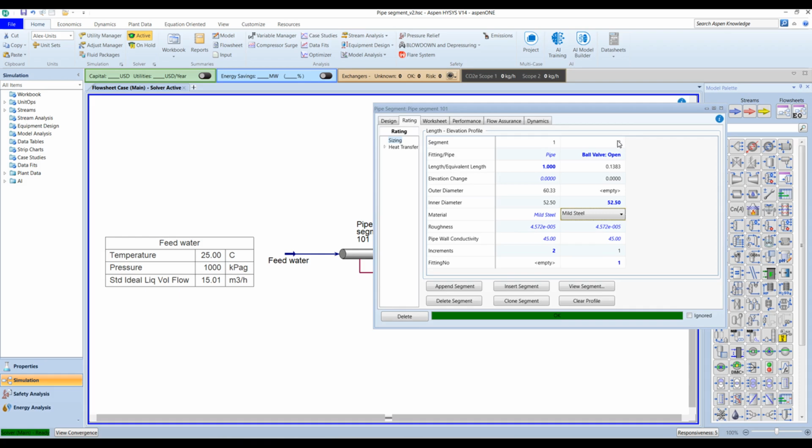And at the end of the ball valve, we want to have that 174 meter pipe run. And to do that, you don't have to do anything fancy here. You just come here, you clone this one, because this is just a pipe, right? This is a 1 meter pipe, but you want to have a similar pipe with the same dimension. So you come here, you just click on that one at the top and you say clone. It will put another section of pipe after the valve.